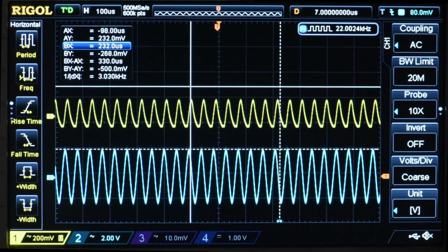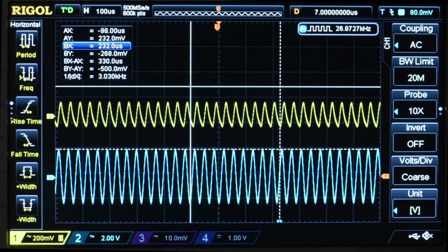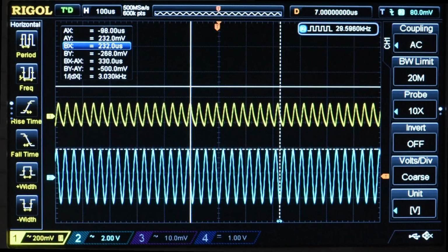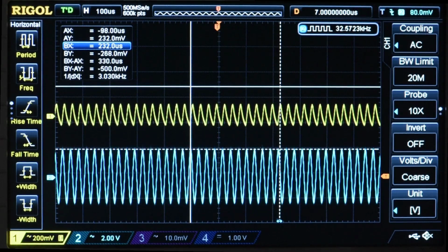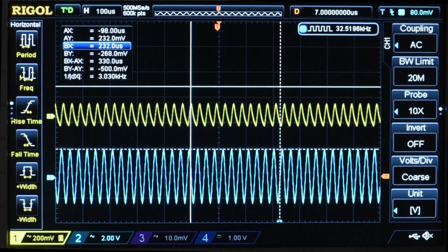Here, I switched the digital filter to a 4x averaging and doing 625,000 samples per second and 625,000 DAC updates per second. Amazing how much better things look doing 50 times more samples per second. I can just sweep up in frequencies, no aliasing problems. And now the input signal is not being destroyed by the chopped up output, so I'll have a better idea of the input signal that is getting through.